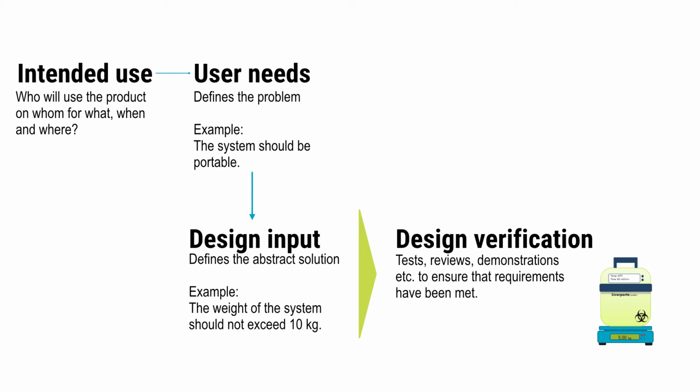A lot of people will think that verification is testing, but it could be using other methods as well, like reviews, demonstrations, or analysis to show that the requirements have been met. For example, if you state that the expected service life of the medical device is 10 years, you will most likely not show that this is true by using a medical device for 10 years and checking that it still works. No, you might be doing a careful engineering analysis of the materials and components included and maybe combine it with some accelerated tests to draw the conclusion on what the expected service life is. There are many different ways to show that a requirement has been met.